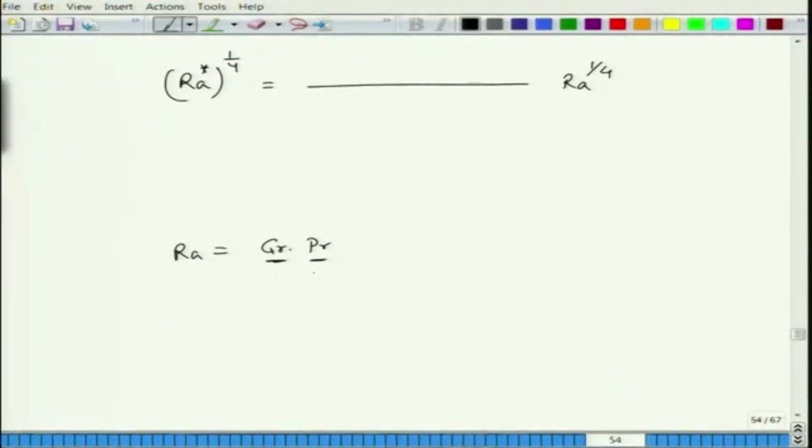So, that is the normal Rayleigh number. Now, for this case we are modifying it, and here comes the effect of the geometry in the form of the natural log of the ratio of the inner diameter for the cover system and the outer diameter of the absorber tube, multiplied by this b to the power 3/4, which I am going to tell you what is b, and d naught to the power -3/5 plus 1 over d c i to the power -3/5, and this whole thing powered 5/4, okay, and that multiplied by the normal Rayleigh number to the power 1/4.